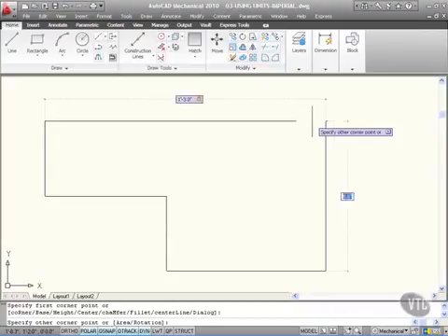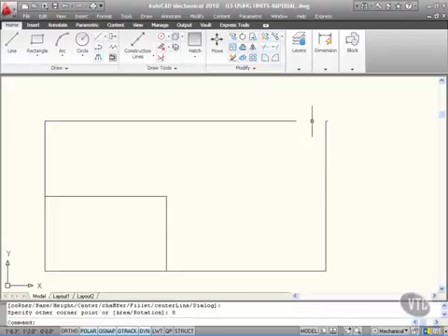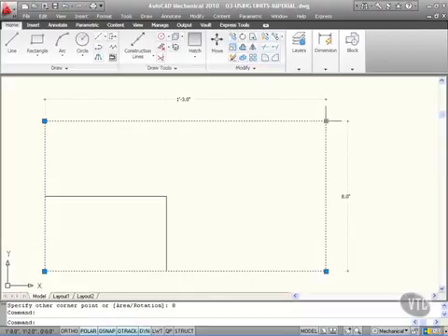I'll leave that one at 8 inches there, so I'll just type in 8, press enter, and it's drawn a bigger rectangle that is actually 1 foot 3 inches by 8 inches, as you can see there when I hover over the little blue grip there after I've selected the rectangle. So that's feet and inches using imperial units.